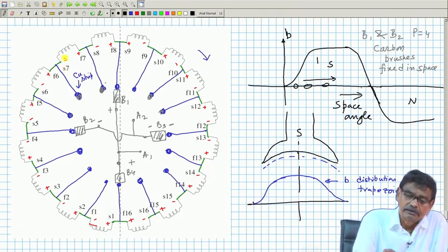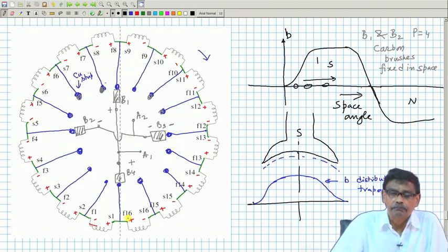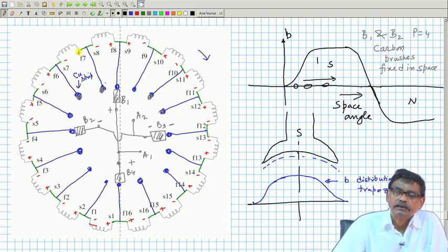After assuming some direction of rotation, generated voltages were shown, and then we found that no matter which coils occupy this particular position, which is presently occupied by the 7th coil, whether it is 6, 5, whoever comes here, because these things are rotating, they cannot but have this polarity of induced voltage, and whose magnitude will also be the same.